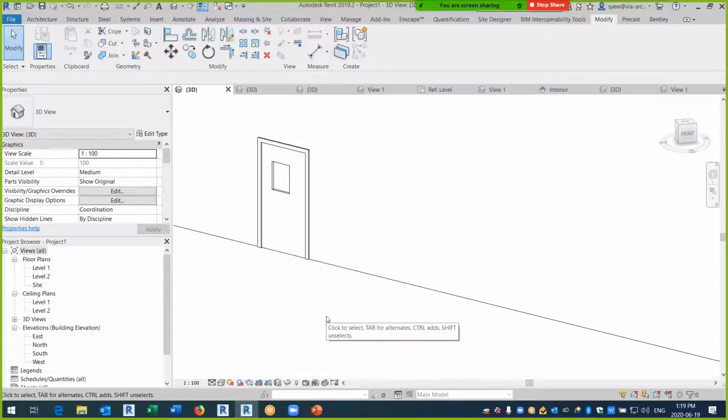This means you can do the same thing if you want to change kitchen cabinets and such. But the only issue I don't like about this is that it will increase your file size. If you have to do multiple panel types, your door type could reach about 1 megabyte. So assume this door is going to be used on multiple floors, then you're going to run into problems. So pick and choose your battle.